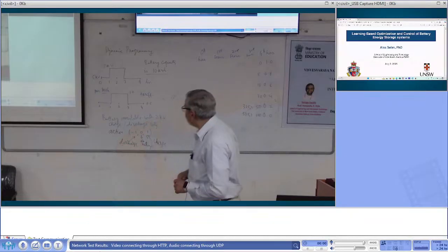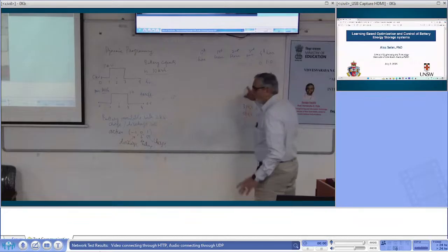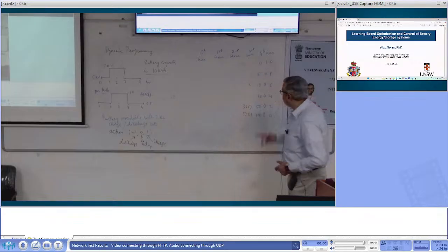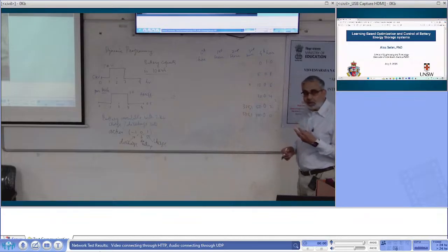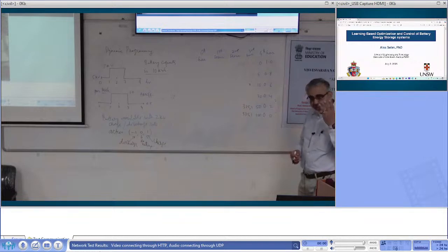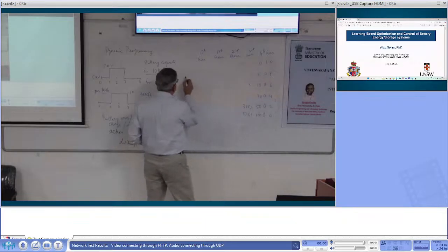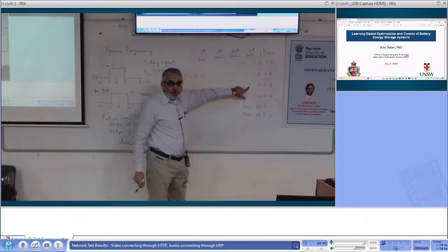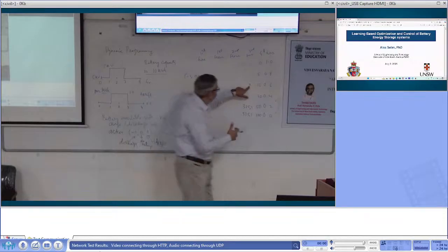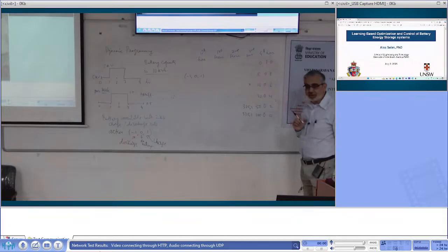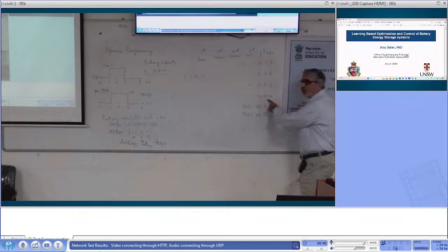So if the rate of charge is this one, let's look at this. If we are here, the rate of charge is 0.6. So there are 3 things I can do: -1, 0, 1. If I discharge from here, what will be my SOC at the end of 4th hour? 0.4. So if I end up at 0.4, the penalty is 30 here.